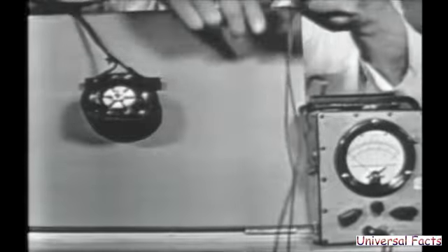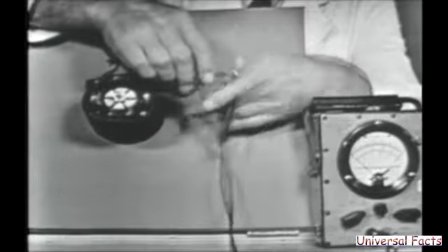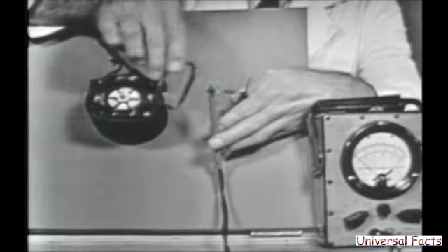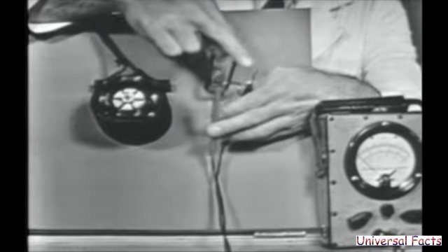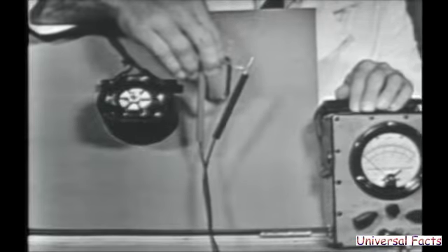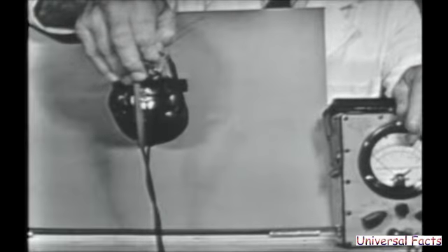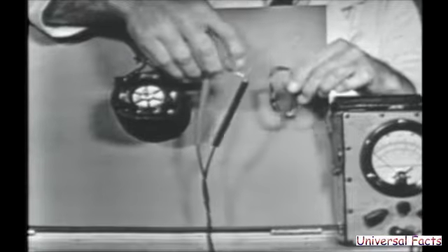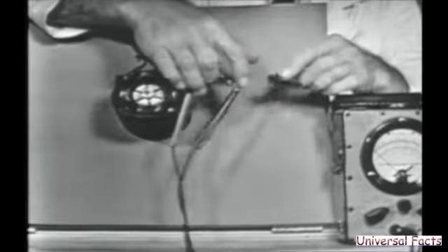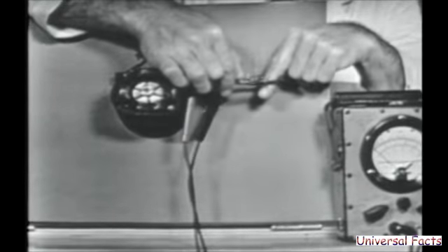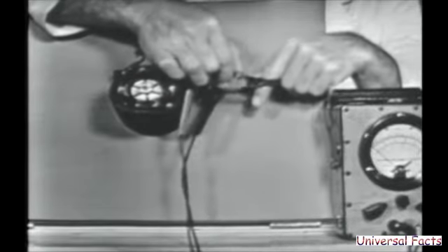All right, help us out. All right, item 4, the rotor acts like a magnet. Well, it actually becomes an electromagnet and follows a rotating magnetic field because of induction. Okay, and we proved that with this little loop of wire, the resistor and the PSM6. We put the loop in the field windings, and the PSM6 showed us that we did have a voltage induced into the loop, causing current to flow. Once we had current flow, we know that the loop had to become magnetized and exhibit a north and a south pole. And once we get it magnetized, it has got to follow the rotating magnetic field.